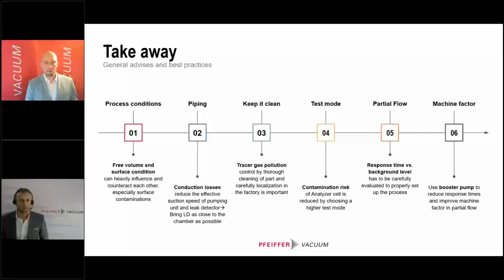Yeah, thanks. What I presented to you in the beginning is the process conditions, what I summarized as the free volume and the surface condition. These can heavily influence and also counteract each other, especially the surface contaminations. If you have oil remainings, this will enlarge the cycle time of your pump down.